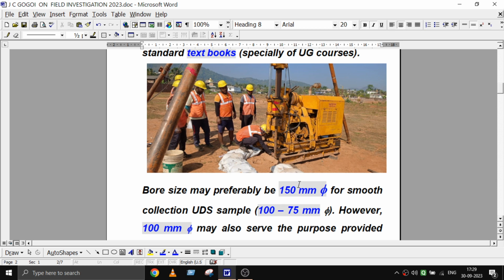by the cutting consolidation apparatus, where one sharp portion is there, almost like an undisturbed split sampler where the area ratio is very low. So with the help of that portion of the consolidation apparatus, we can cut out the required dimension from 100 dia for the consolidation test.